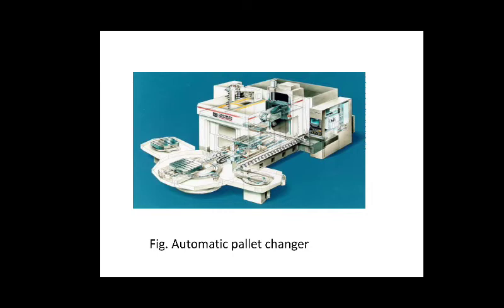These pallets simply move for interchanging their positions on the machine table. While machining is being done on a job kept on one pallet, the other pallets are accessible to the operator for clamping and unclamping raw material or finished product. This saves a lot of material handling and setup time, resulting in higher productivity.